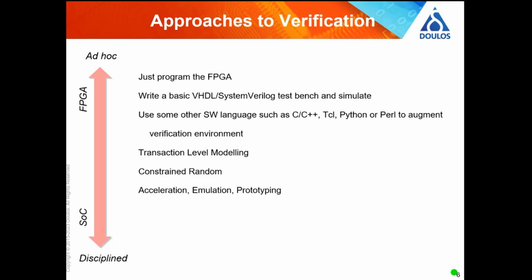What I've been involved in a lot is FPGA prototyping. My background is designing chips, and if you get a chip wrong, it's very costly, as I'm sure you can imagine. And I mentioned a validation failure earlier: the chip met the spec, but the spec was wrong. So after that, we always did FPGA prototyping. We always got our digital TV chips, connected them up to test gear in the lab, put them in the back of a van and drove them around the countryside to check them before we committed to silicon. And if you're designing an FPGA, you can't prototype it, because what would you prototype it with?